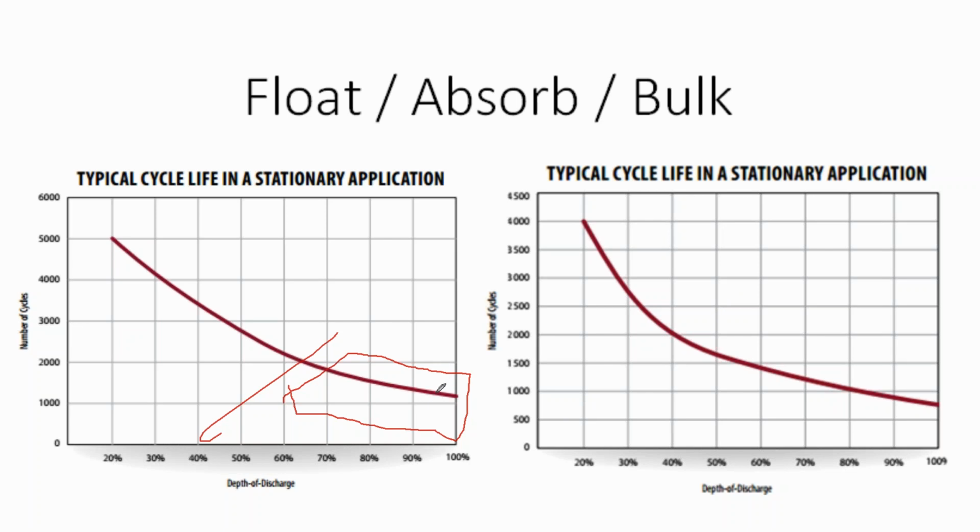But still, even so, the manufacturers give you a cycle life related to your warranty when you're operating down in that range. I mean, there's this idea that if you fully discharge a lead acid battery, it won't charge all the way back up again, but that's not the whole picture.